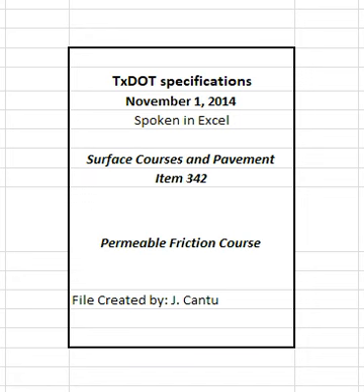Allow adequate time for emulsion to break completely before placing any material. Prevent splattering of tack coat when placed adjacent to curb, gutter, and structures. Roll the tack coat with a pneumatic tire roller to remove streaks and other irregular patterns when directed.